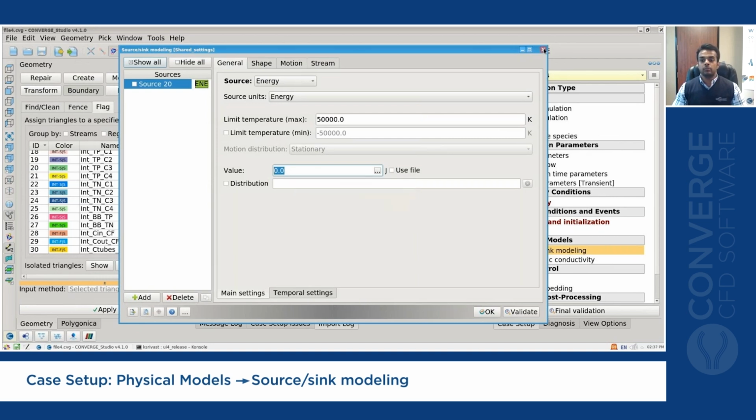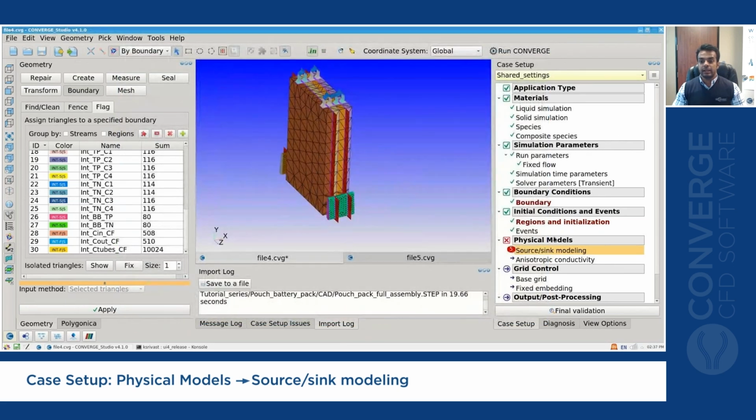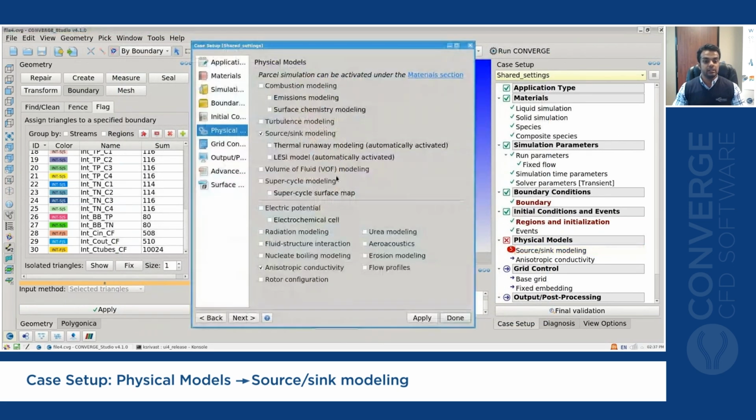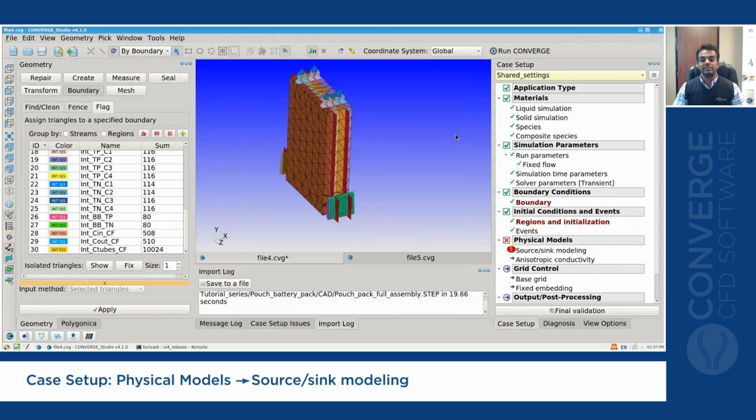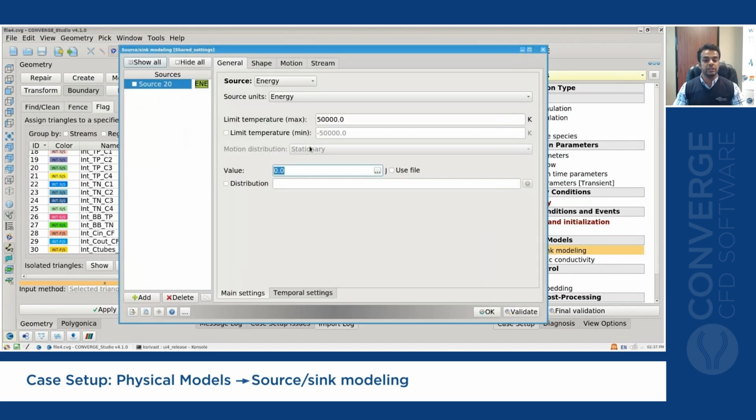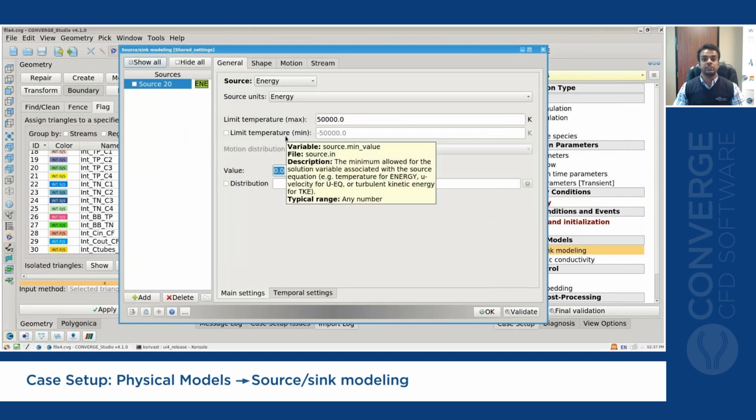We could be more detailed, and we do have a 3D electric potential solver, which includes electrochemical solution. This is a more detailed solver. We could incorporate this, but we want a quick and rapid simulation. So we are going to use a lumped parameter model called the battery equivalent circuit. The battery equivalent circuit is a 0D model that incorporates an electrothermal response.